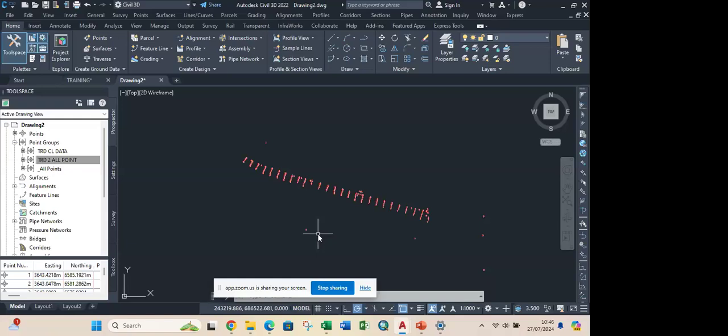So this is all for point importation. Just like I stated initially, the first thing is where it gives you your points, note the easting and the northing, which one comes first. Then know the format. After you're done with that, you save the work in CSV comma delimited. Most surveyors nowadays normally send a CSV file to you when they extract it from the differential GPS.